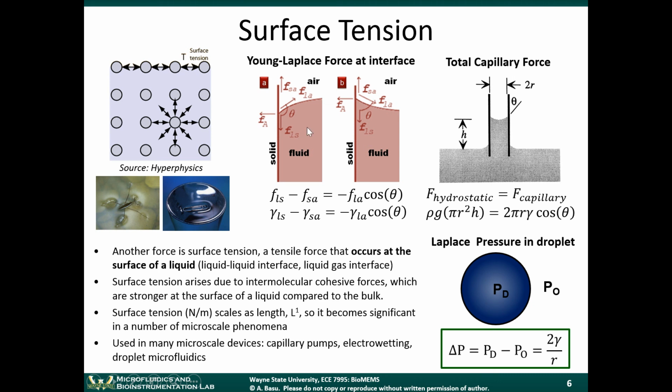Now if we get into more specifics of it, we can look at the Young-Laplace forces at the interface. And it's given by this equation here. Now the force, let me just describe what this is. FLS stands for the force at the liquid-solid boundary. So that's given by this right here. FSA is the solid-air. At the solid-air interface there's a force, and at the liquid-air interface there's another force. Okay. These are two examples of capillarity. I'll show a little bit more on this slide here.